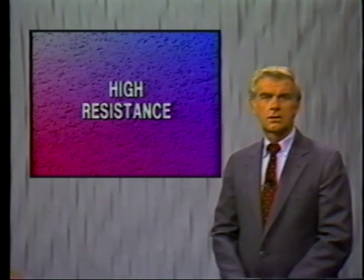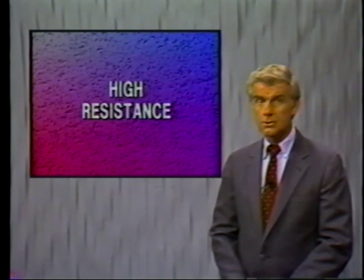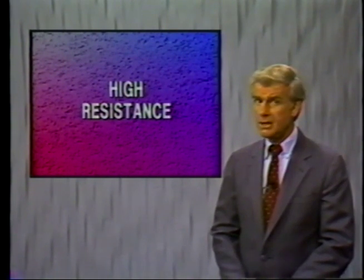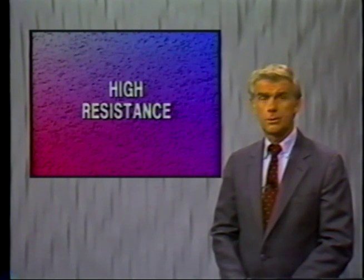High resistance in a circuit is the kind of electrical problem that gives technicians the most trouble in diagnosis, even though the correct test steps are very easy to do. These problems are typical of dim lights or slow-turning motors.